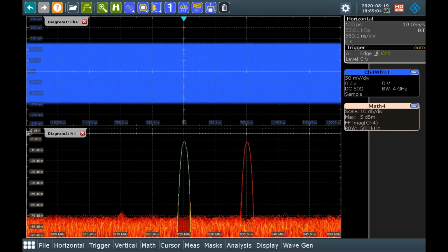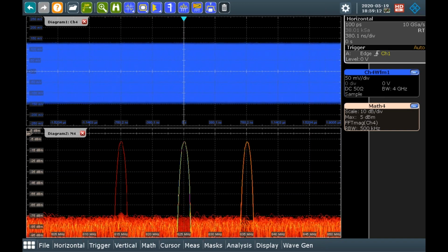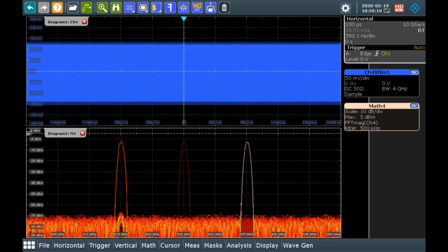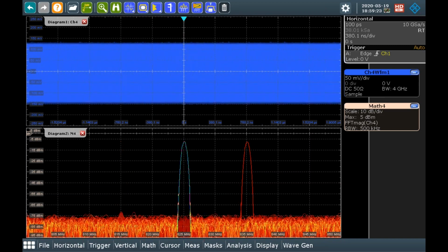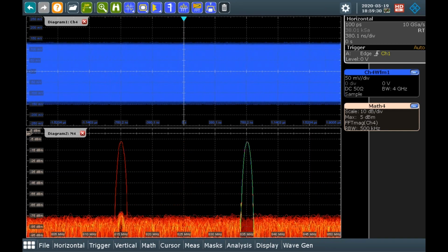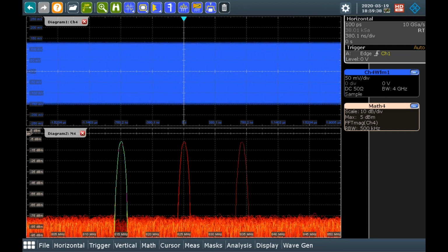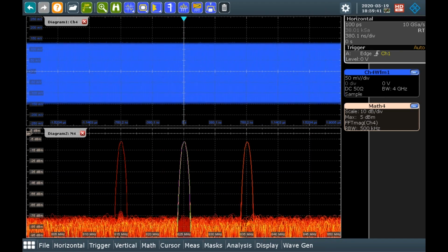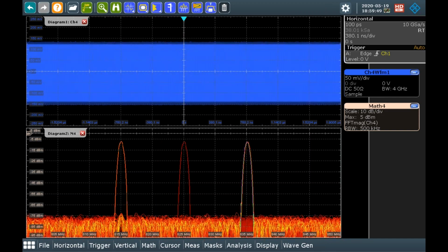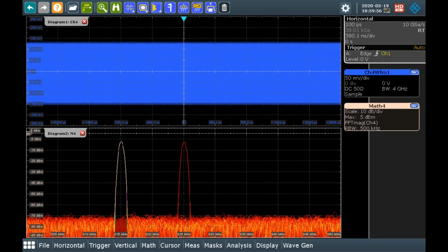Right now on the top, the blue trace is the time domain, so that's voltage versus time, everything we've been talking about so far today. On the bottom, we've got power versus frequency. This is what you would typically look at on a spectrum analyzer, but we can do a Fourier transform on the scope and get a very, very fast FFT. A lot of times people are hesitant to use these on a scope because they're too slow. This is incredibly fast. It's a very interesting, cool way to look at multiple FFTs at once, so multi-channel frequency domain analysis. An oscilloscope has 4 channels. You can use all 4 channels as a spectrum analyzer input. They're really good at low frequency spectrum analyzer work, starting down close to DC.